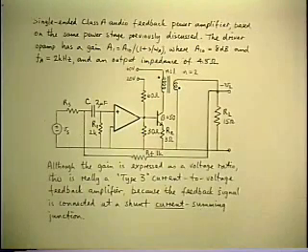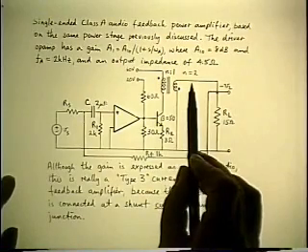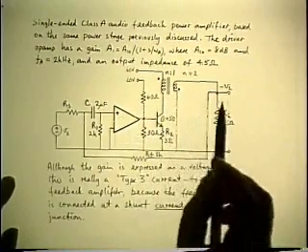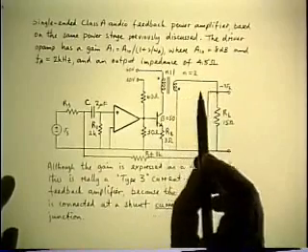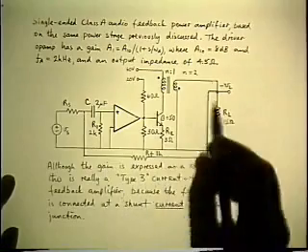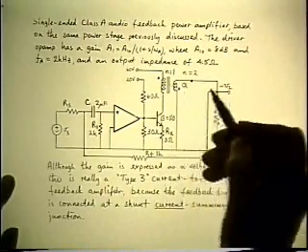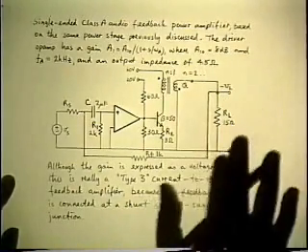So just as an example, let's go back to this audio amplifier that we'd had before, because in this is a case where we chose to do current injection. And the point where we did the injection was at the secondary of the final output stage, because we'd modeled everything before that point into an equivalent current generator, and the only thing left externally was the load and the feedback path. So this was the point which had labeled Q. That's where we did shunt current injection on paper.